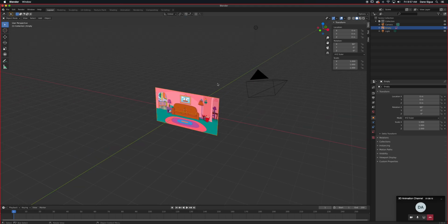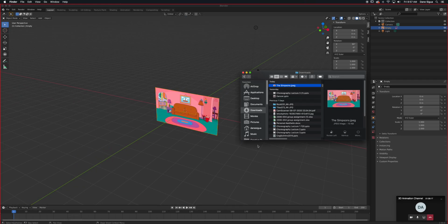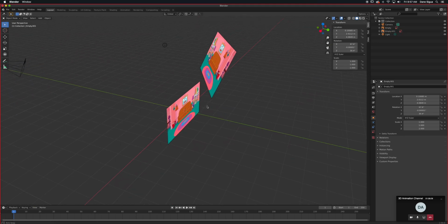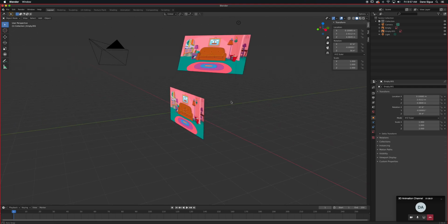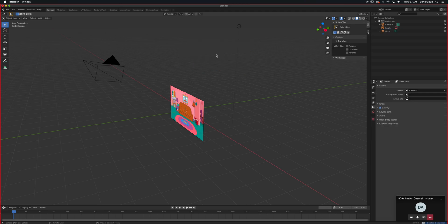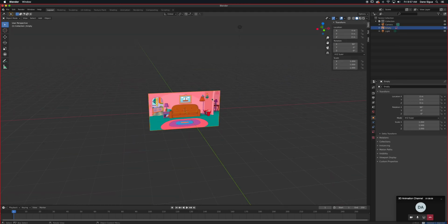I'm going to have an angle like this. Okay, I'm going to have Finder in here and I'm going to drag it in. So if I drag that in, it looks like it's flat, but in reality it's not. Look, it's based on that angle. So when you drag your photo, make sure you're in the front viewport, flat, orthographic, okay? And if you made a boo-boo, you can always just select that and then type in the values here, but it's just less work when you do that.